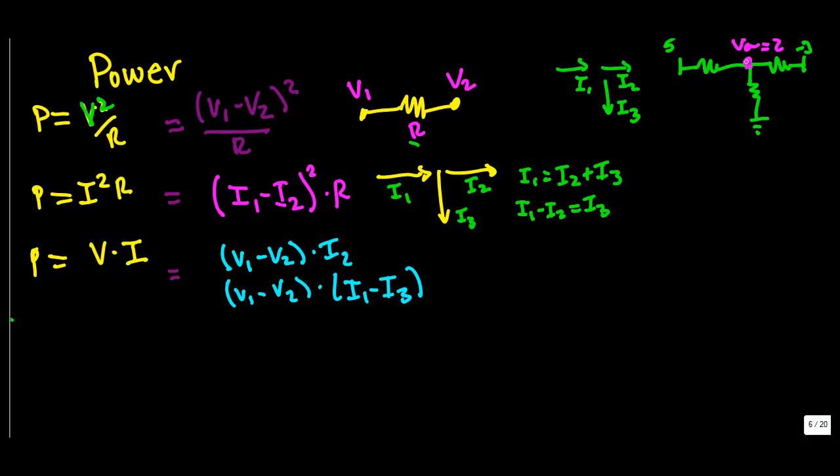So basically the way we did the equations, we were saying, okay, well VA minus 5 volts over your R1 resistor plus VA minus your -3 volts over your R2 resistor and so forth. So basically what that means is when you are setting a number like VA minus 5, you're saying that the current is going to flow from VA to the 5 volt source, or from VA to the -3 volt source.